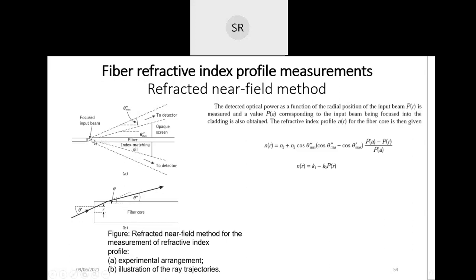Means for a given particular fiber, there is a maximum acceptable angle, and above that your signal will be refracted. So now that's one. This is about a part of refracting a signal out of the fiber, that is, into the cladding layer or out of the core here. And those within that acceptable angle will be propagating through the fiber.